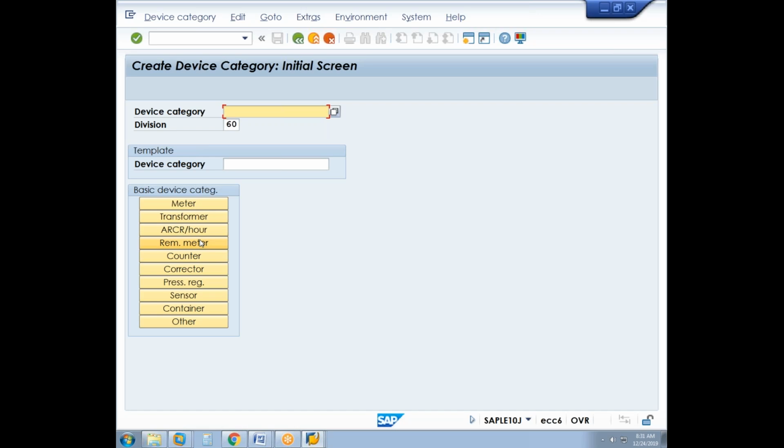Okay, that means the street lights are on and off based on the signal sent from the ripple control receiver. And in some countries, they use it for load balancing. Whenever there is suddenly a surge of power in a particular area, using the frequency imbalance, the ripple control receiver will send a signal. So it will put off the supply to the area, and then after the loads are stabilized, it will resume the supply to that particular area.